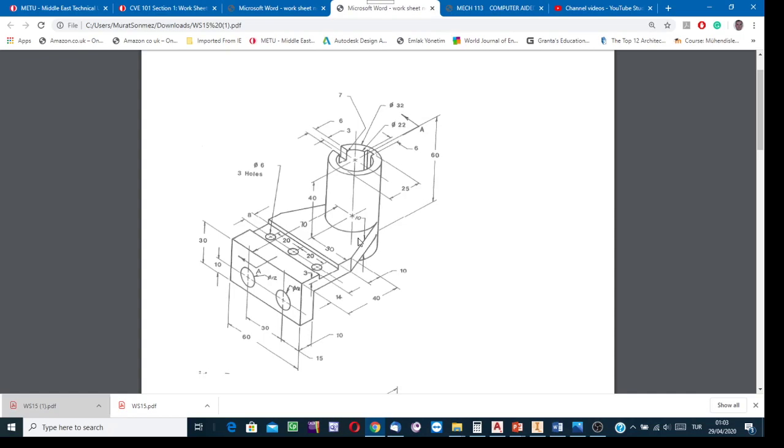But if the volume to trim is too much, and some surfaces are curvy, so the cutting method is not a suitable, economical, feasible method, then in a virtual environment such as Inventor, do not start from a rectangular prism. In such a case, you may use either a completely adding method or partially cutting, partially adding.